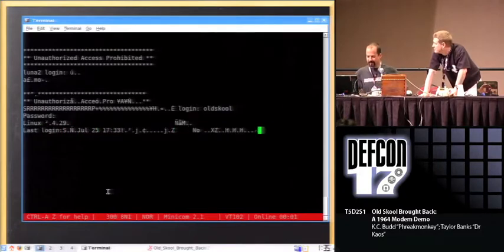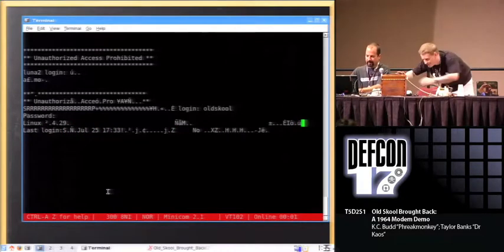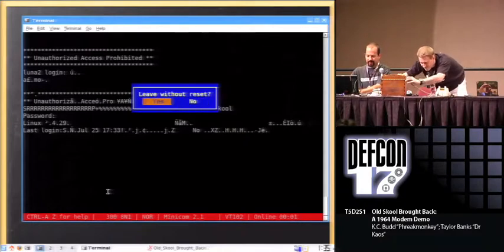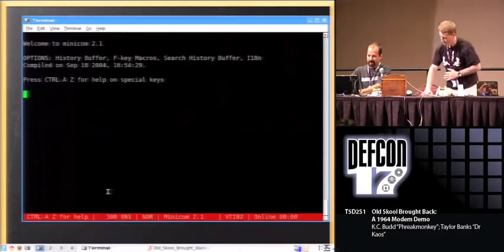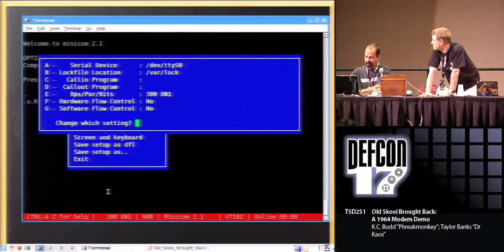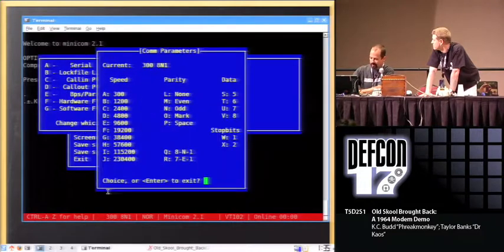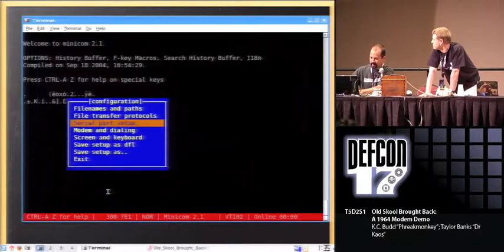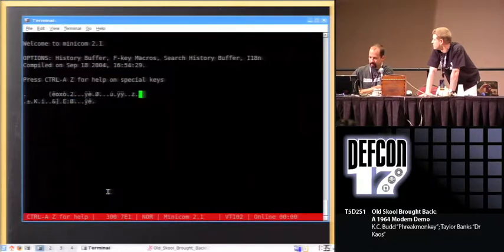I think we got a, let's just leave it. If I rerun Minicom, it'll probably fix it. No. Man, it didn't like that at all, did it? Let's go to 7 data bits so that we don't have the high characters because we're only doing ASCII anyway. That didn't help. All right, let's call it back.